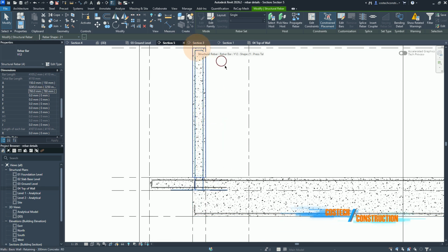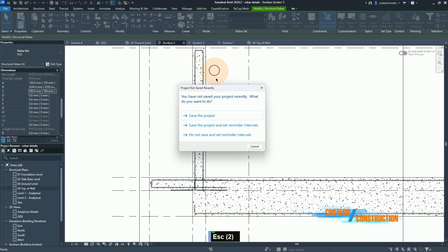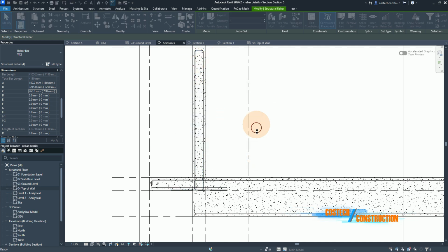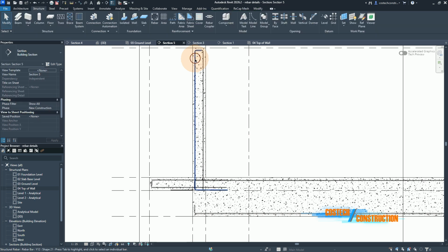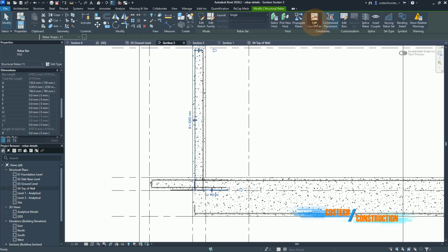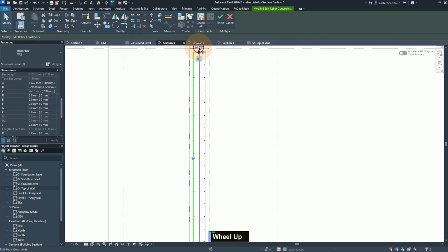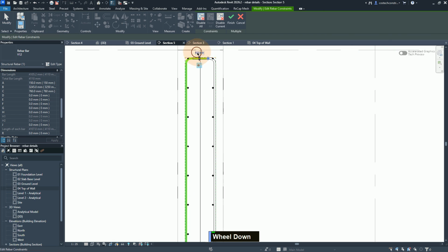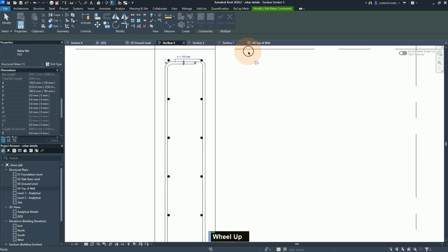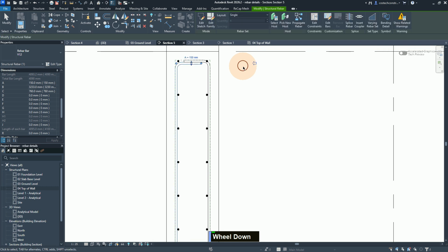Only what we can edit is perhaps a small distance for clash prevention. What I mean by that is, I will select this at the left side. Then we can go to edit constraints. Go to edit constraints. Now I'll select this top handle and give a value of -12 at the top. Then hit finish. Now we can hit escape.